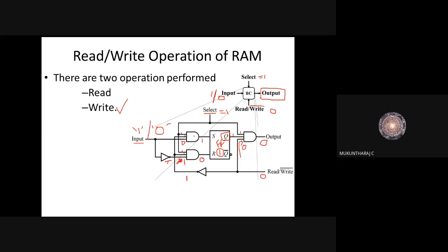So now this AND gate has 0 on the input line, one of the inputs is 0, so definitely the output of this AND gate is 0. Then for the second AND gate, 3 inputs are set with logic 1, so definitely the output is logic 1.